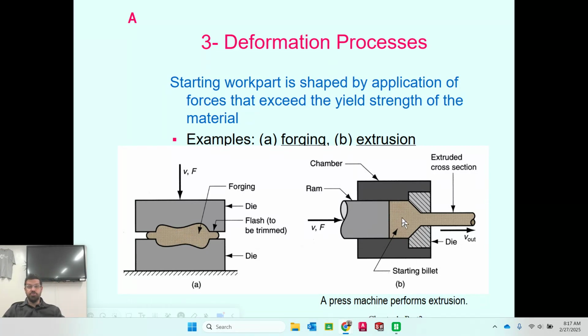This over here is called extrusion. We've heard that word before in our SolidWorks careers, extruding. Basically, with extruding you have a certain amount of material, and you have a press that pushes on the material. Over on this side of your extruding machine, there's a specific hole. As you press a larger block of material and the only out that it has is through that hole, it takes the shape of whatever hole that is.